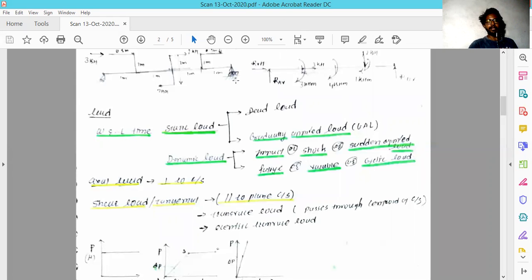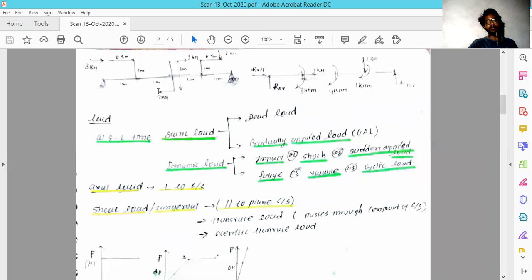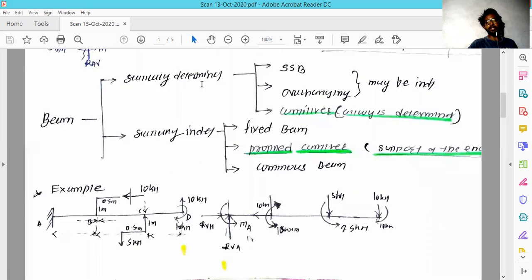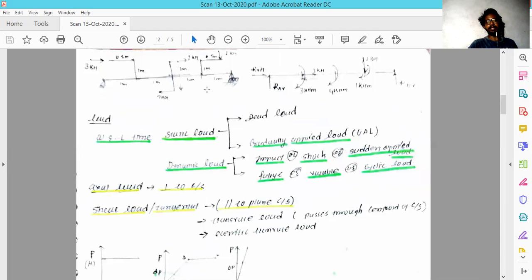And now, if you move the 3 Newton meter from the hinge support, here you have this link, a 1 meter vertical link, and a 0.5 meter horizontal link, and one at the end of the horizontal link. You can see the 2 kilonewton force is going to act in the vertical direction. So what will happen here is one torque is going to be generated at that point, and the force of 2 kilonewton is shifted to the joint point of that beam and the vertical line.